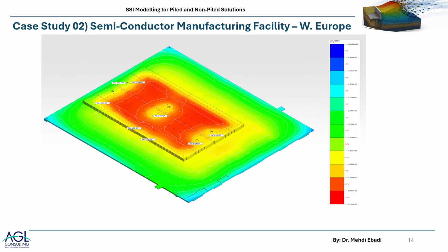So we had higher settlements on the upper side of the foundation with the pattern that you can see. And the way we wanted these results to be communicated to the structural team was to have them both in terms of settlements and in terms of angular distortions.